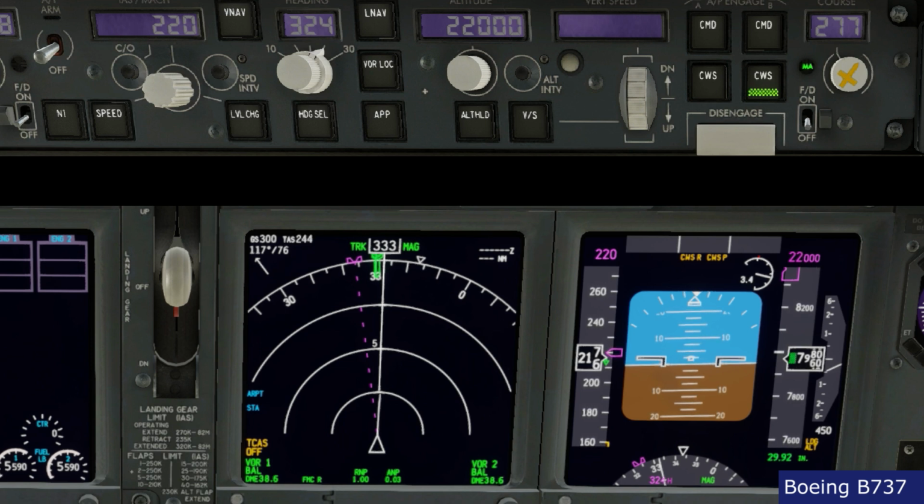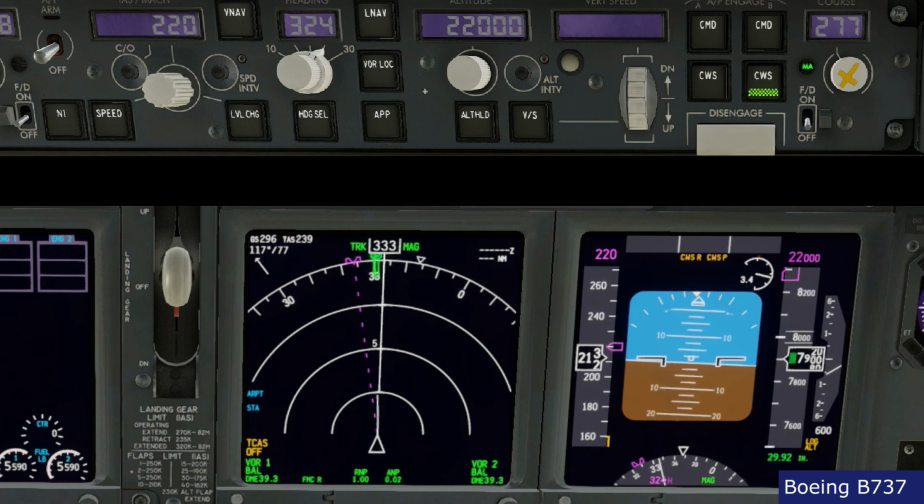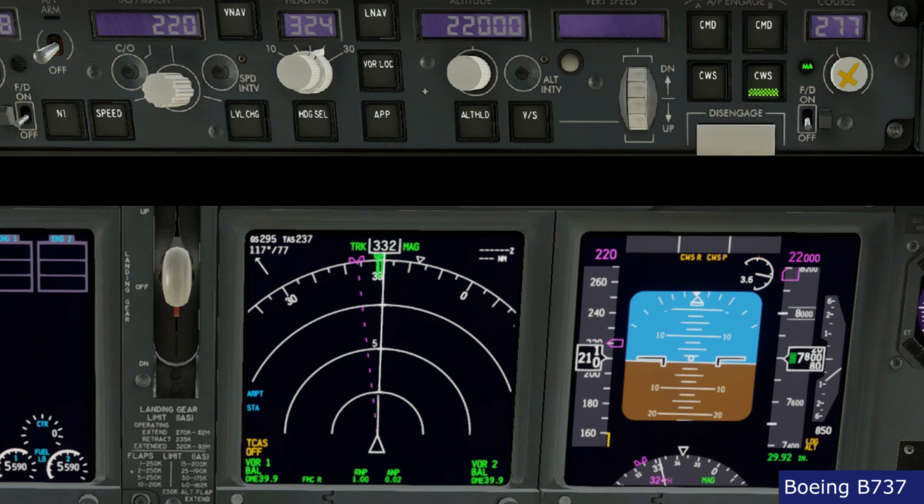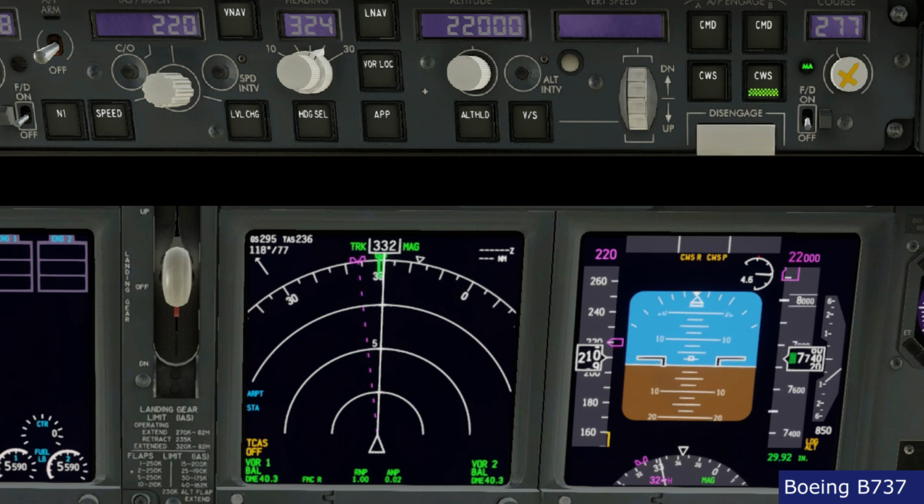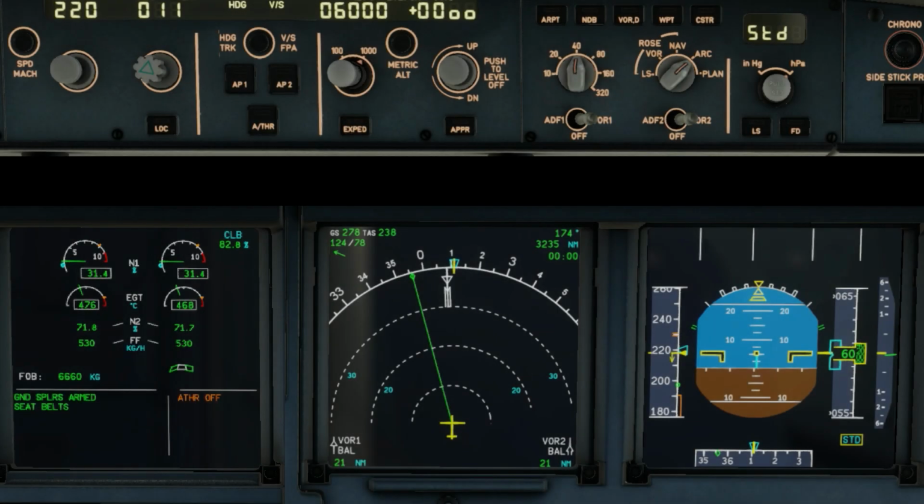I tell you, in reality the control with steering is even more precise than this. We are losing the pitch by more or less 1 degree. Normally the autopilot, or anyway the control with steering function, is much more precise than this. There we go. So the scope of this exercise was just to demonstrate that the control with steering is maintaining the pitch constant. I am trying to replicate this exercise on the Airbus 320.